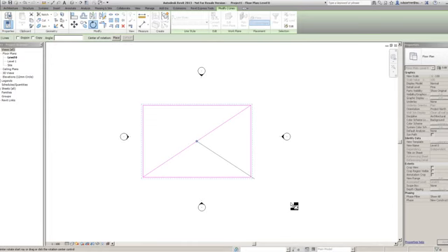That's fine. Now obviously in AutoCAD, basically what happens is it gives you your first line of reference straight out to the right hand side, like the 3 o'clock location, and then it's just asking you for the angle. In this one, it allows you to put in your first point of reference. So what I'm going to do, I'm just going to be a bit of a rebel. I'm going to come in the completely opposite direction. I'm going to start over here, left click. And then I just rotate it around either this way, counterclockwise or clockwise, it doesn't really matter.